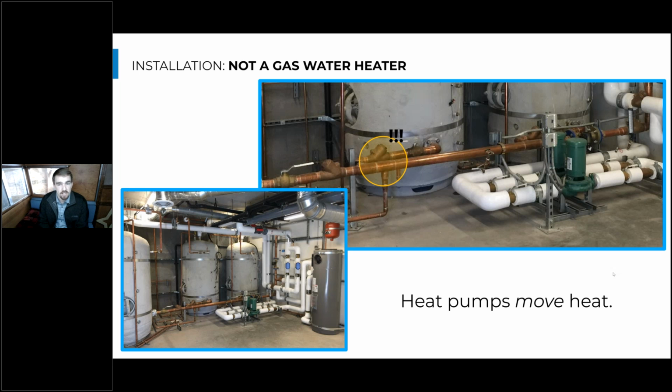But some best practices don't apply to heat pump water heaters, so you need to think carefully about and coordinate with your engineer about those best practices if they deviate from the drawings. One I've seen really consistently as I start up heat pump water heaters is the addition of check valves in the makeup line to the tanks, which usually works really well, but in some heat pump water heater designs, the heat pump will actually pull cold water out of the tank through the same line that cold makeup water enters the tank.